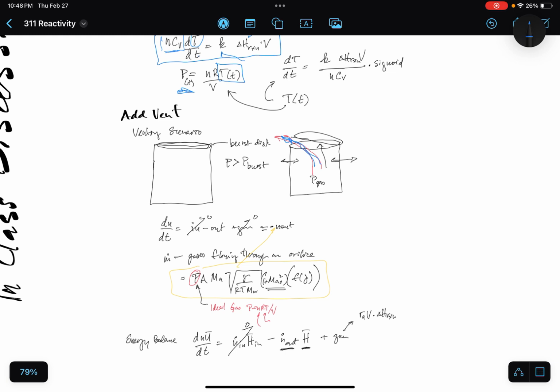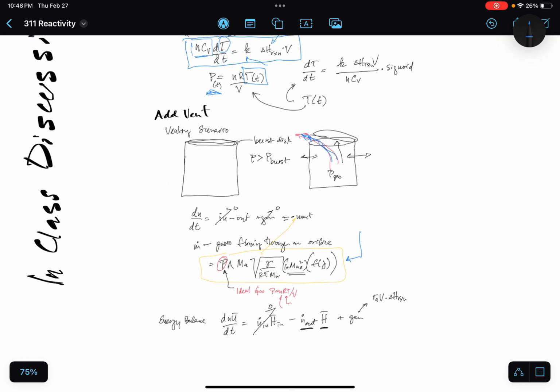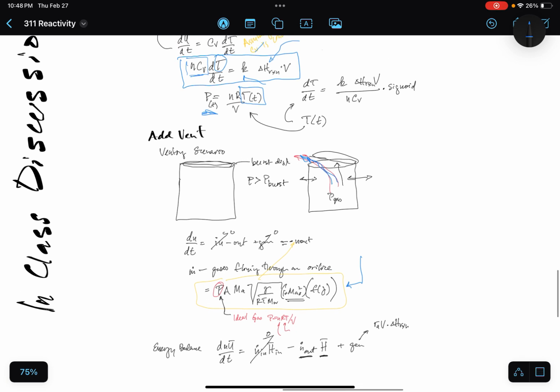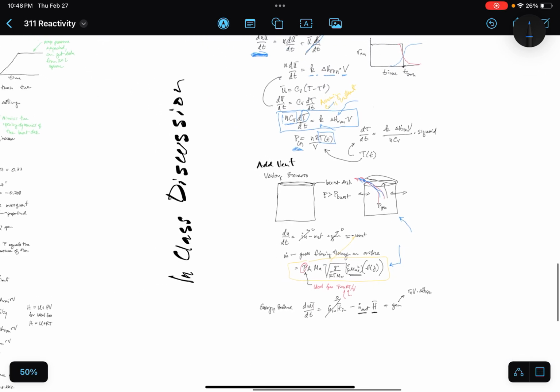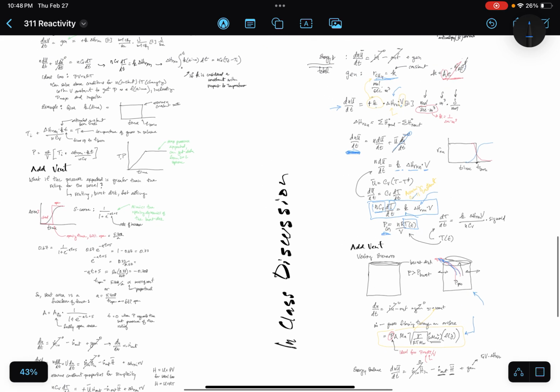In this case, now you have moles of gas out or mass out, and you can get that from gas flow out of an orifice. In this case, it's maybe frictionless as a first estimate, and you can get how that pressure as a function of time is what would happen to your vessel. That's a way that you can estimate violence from a chemical reaction.